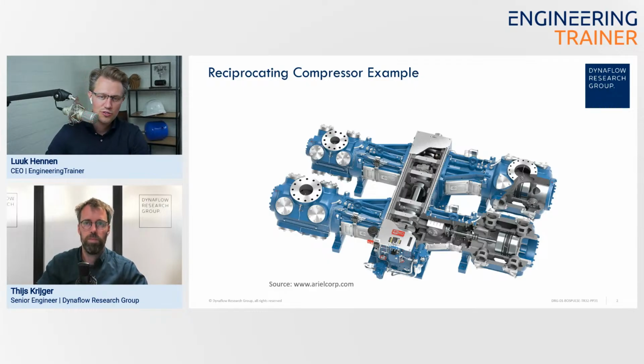So we were discussing the equipment. We've got those pistons going up and down, or let's say from the left to the right, based on the crank movement. So how does that result in the pressure? This piston is moving back and forth inside a chamber, and connected to that chamber are valves, and those will be check valves, so they will only allow flow in one direction.